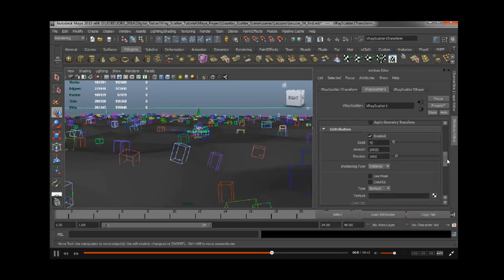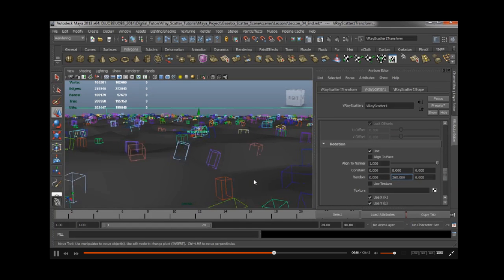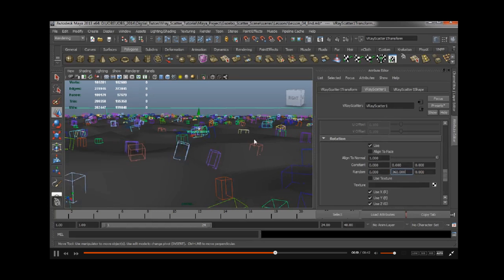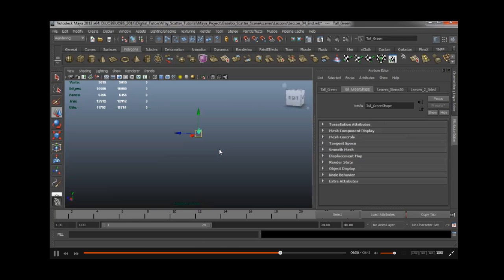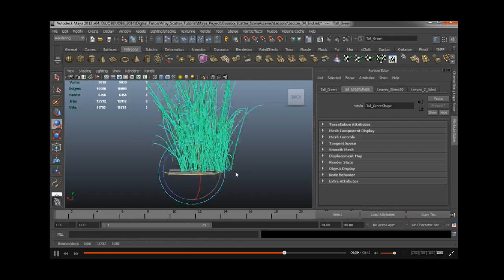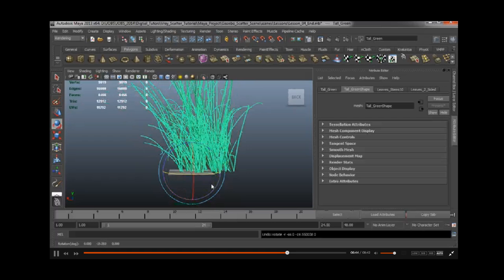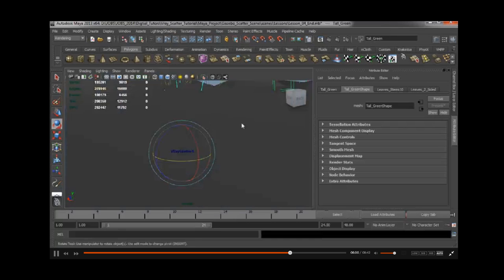And we're just going to do some very quick common things, which is randomize the rotation in 360 degrees. This is going to depend on our pivot, so definitely make sure that the pivot for each of these PaintFX assets, now polygon assets, is at the base of them. In other words, this tall green one, you can see it's at the base, and I'm just quickly sliding the pivots down to the bottom here. It doesn't have to be in the exact center. It's okay if it's pivoting around here when we rotate a little bit, but they have to be at the bottom. Otherwise, we have to start worrying about offsetting them down too low in the V-Ray Scatter, so let's just have them nice and clean before we even do that.